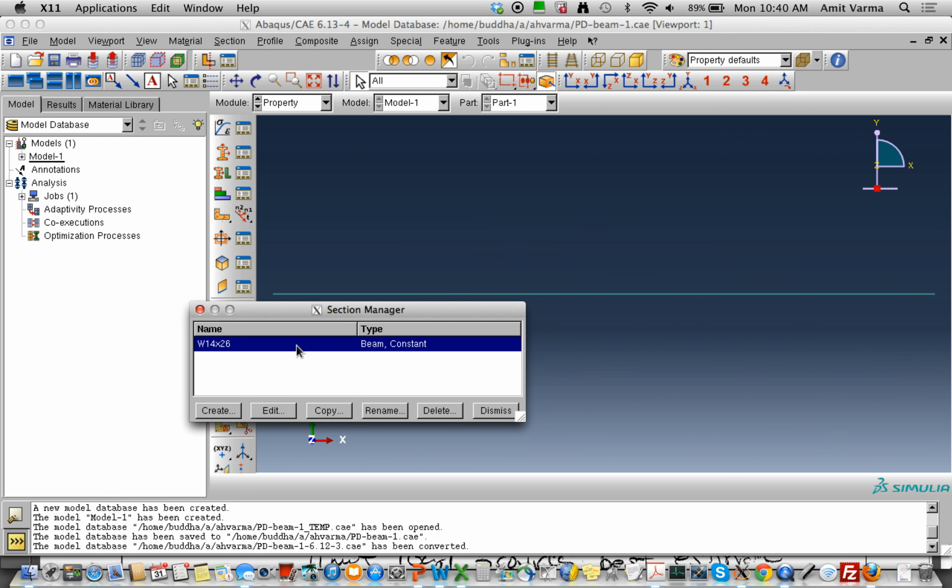Is L the area centroid, or the elastic centroid? It's the elastic centroid. So for the T-shape it is the elastic centroid, so in a T-shape it'll be the summation of Ai times yi divided by the summation of Ai, right? Y bar. And you can notice where it's being defined from. It's being defined from the bottom of the cross section. So you'll put in all those properties.